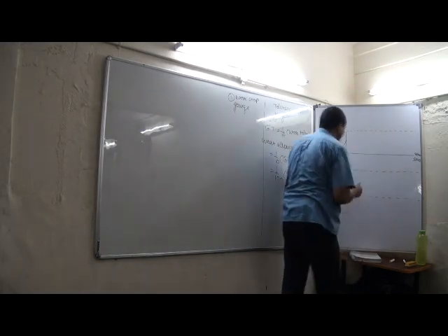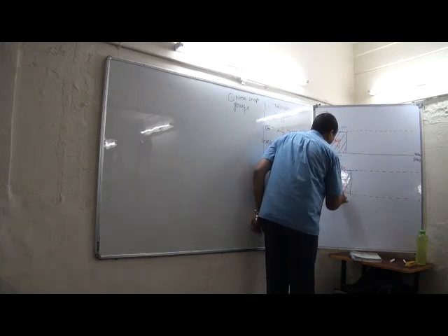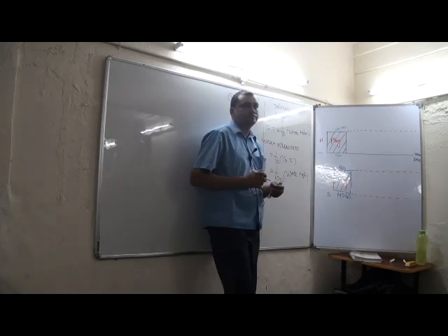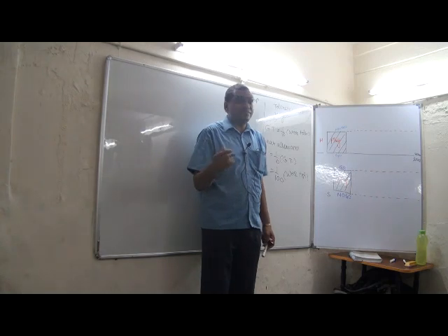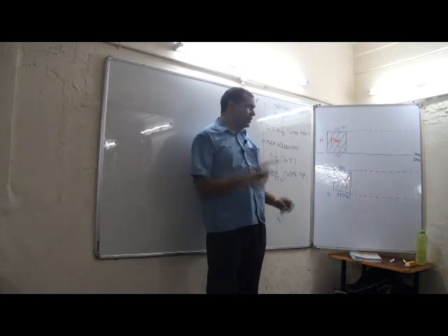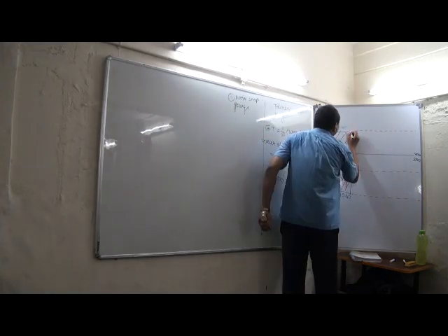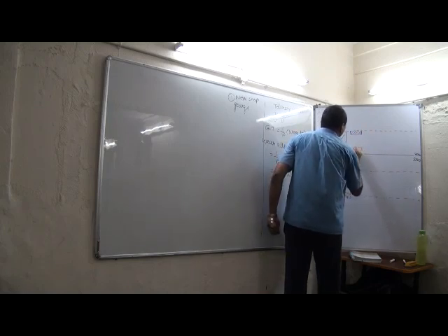Similarly for the plug and ring gauge, go will be designed here, no go will be designed here, and we have to provide tolerance on the gauges, otherwise we cannot manufacture them. The workshop gauge philosophy says we will not produce anything defective. So the tolerance will be towards the work tolerance. This is the tolerance of the no go gauge, and this is the tolerance of the go gauge.